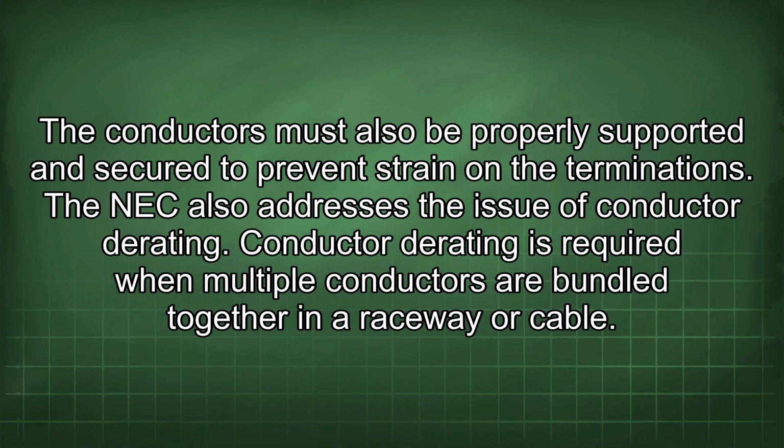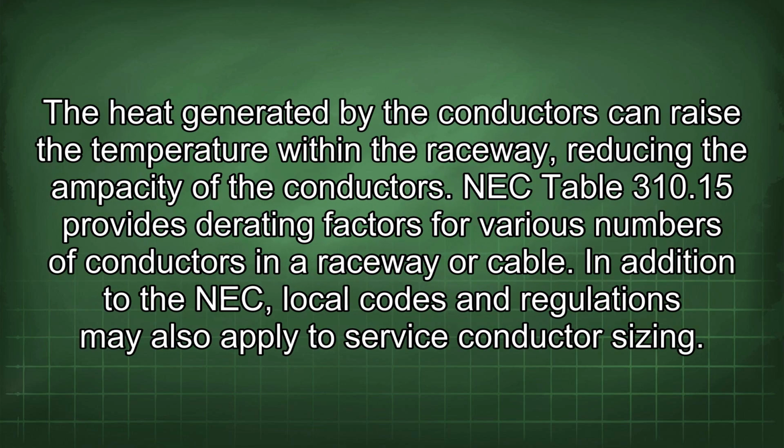The NEC also addresses the issue of conductor derating. Conductor derating is required when multiple conductors are bundled together in a raceway or cable. The heat generated by the conductors can raise the temperature within the raceway, reducing the ampacity of the conductors. NEC Table 310.15 provides derating factors for various numbers of conductors in a raceway or cable.